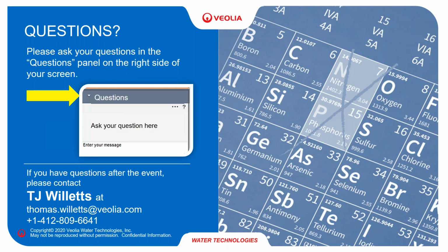Absolutely. So I will start talking about nitrification, denitrification if I see either one of two things on the permit. You're either permitted on total nitrogen and you have nitrogen on the influent, or your permit talks about both ammonia and nitrate nitrite. I've seen both. When you're talking about total nitrogen, I immediately know we cannot just nitrify, because if they measure total nitrogen, they will measure nitrate nitrite, and your total nitrogen is basically not going to change. So we will need to go to nitrification, denitrification in that case.